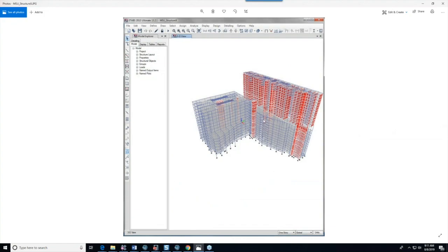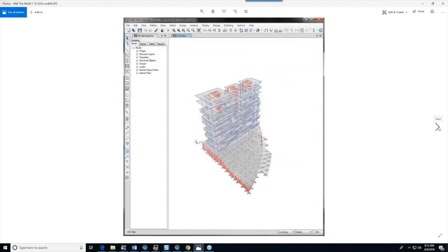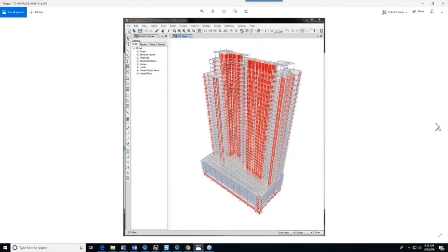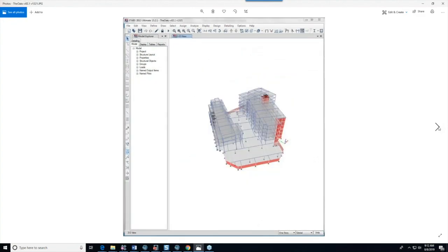There are times when you can, for instance, on this building, there is the need perhaps to define the diaphragms as semi-rigid, because there can be quite a bit of distortion between two different wings. If you have an L-shaped building and you want to find out what's going on at these reentrant corners, then of course it would make sense to model these as semi-rigid diaphragms. But I'm going to look at another building here in particular.